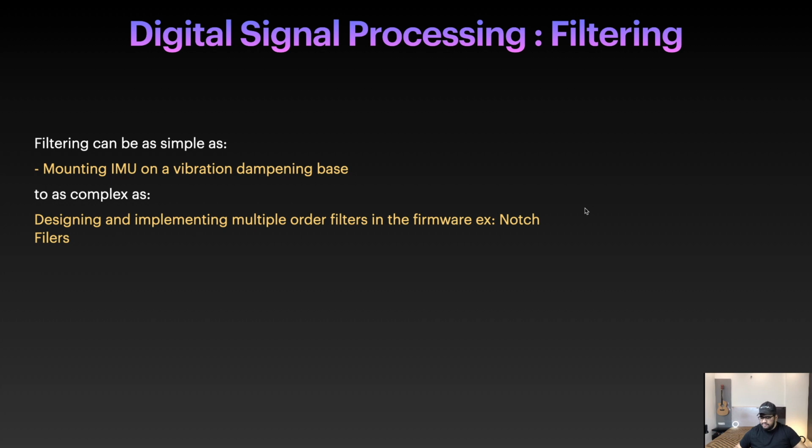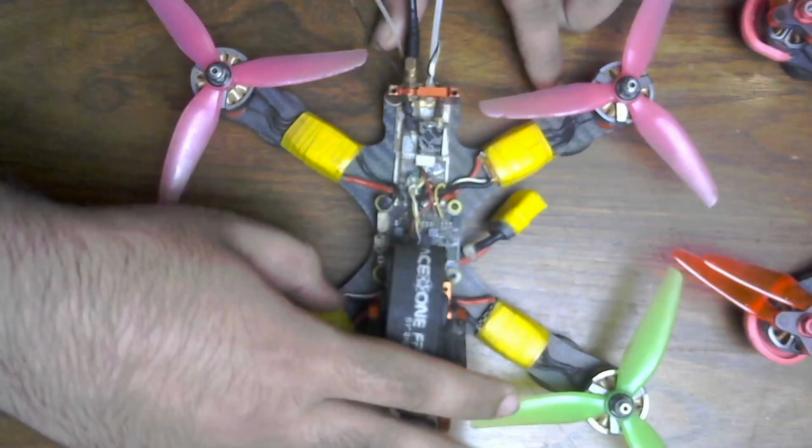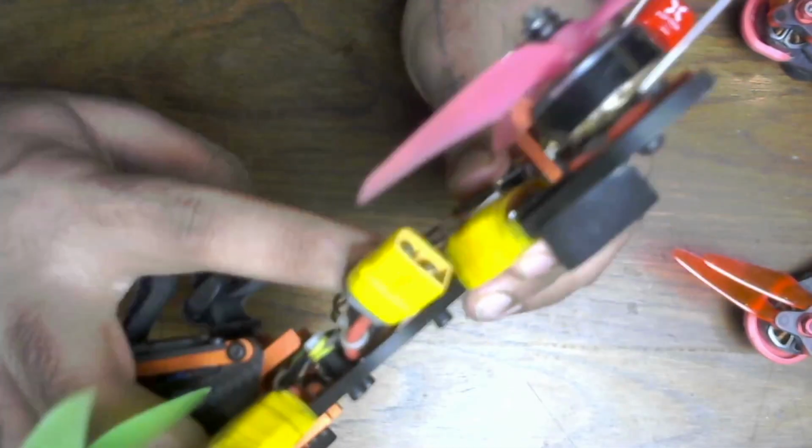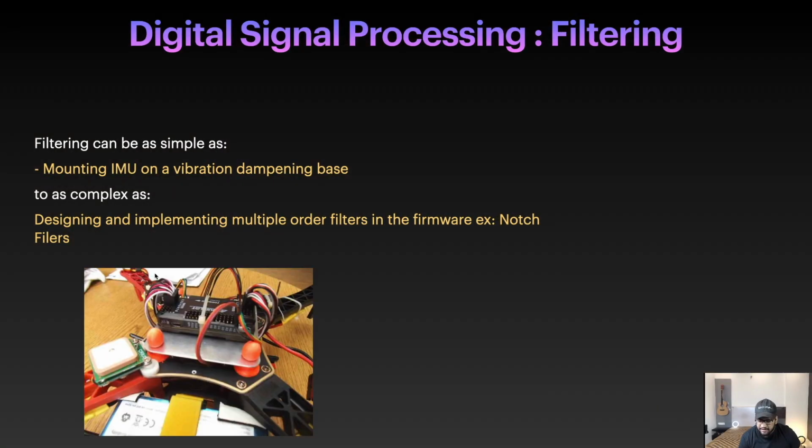One good example I can show with the overhead camera. Here you can see in my drone I'm using these vibration dampening balls. This ensures that there is no mechanical noise in the system, and similarly you can add that in the drone itself. This is a bigger frame which allows you to add these kinds of vibration absorbers, and this ensures that the mechanical noise coming from the vibrations in the drone is reduced. The moving parts of the drones are generally motors, and they create vibration.